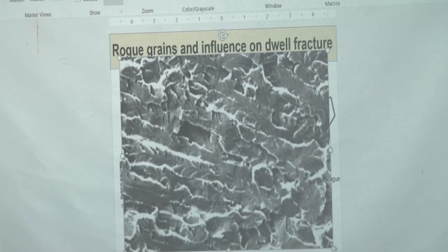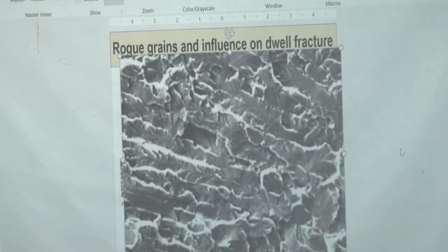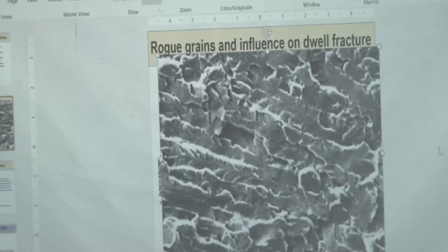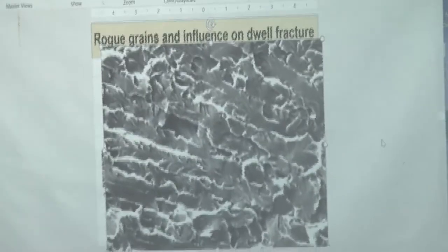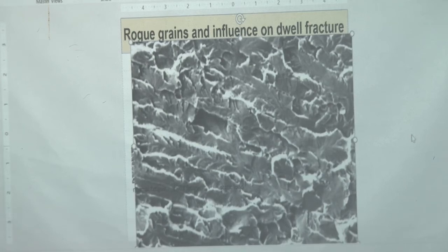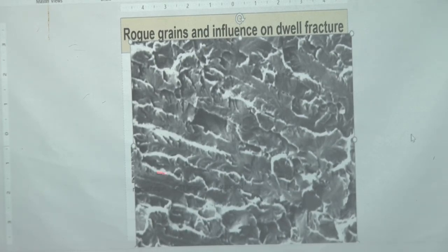There is your dwell fatigue. You have to put this side by side, I think, to get a better picture of it, but you can clearly see the difference. I can see that because I'm more used to it. But you can see this, the planar slip band cracking. See this whole thing? That's a planar slip band cracking. This whole thing is a planar slip band. Well, these are little pieces here. There is another. This almost looks like a cleavage in a way, or transgranular fracture.